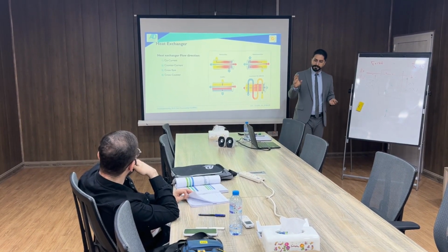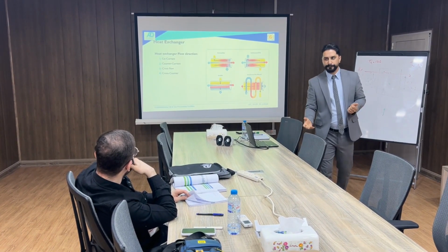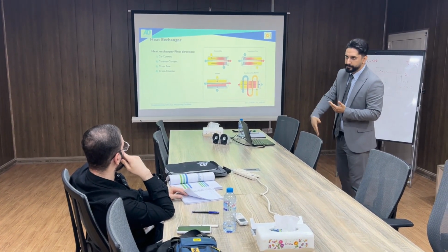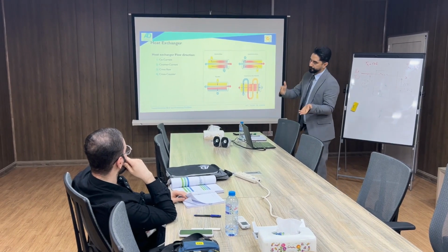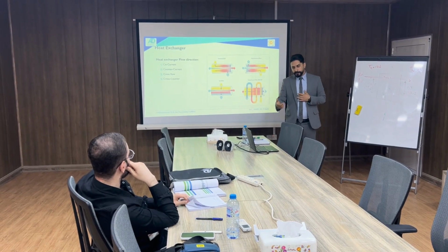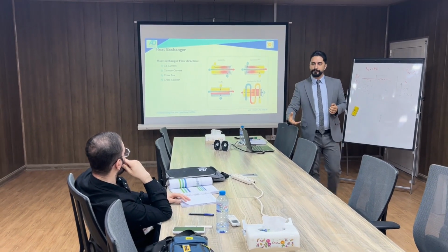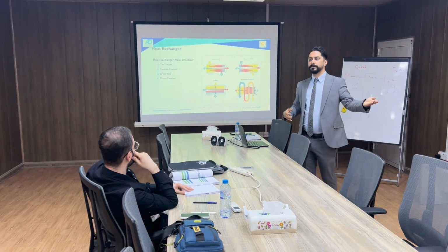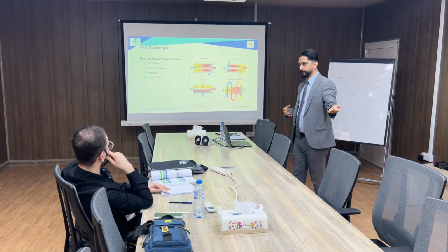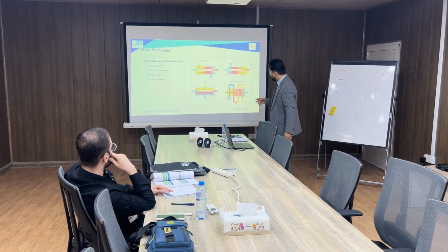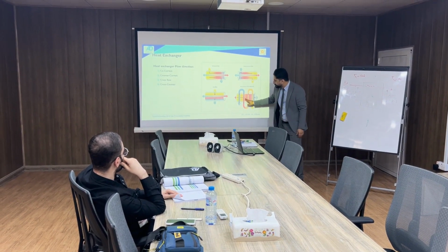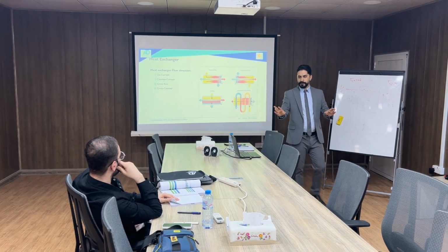And by using software, we can check if it is effective to pass the hot medium, for example, over the tubes in cross flow or in counter flow. But what's important is that, if you remember, for convection, we said that providing turbulent flow will increase the amount of heat transfer in the convection method by a huge amount, okay? That's why they prefer this method of passage by providing baffles, and we will see the configuration of the baffles.